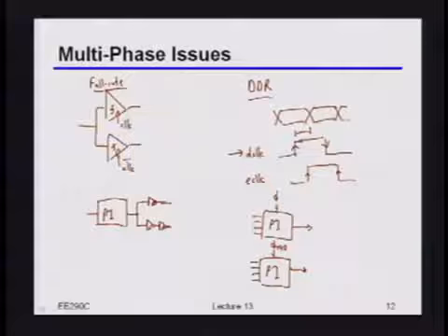So it's not to say that it can't be done, but it turns out there's a sufficient amount of annoyances with doing things this way that people actually came up with a few fairly clever solutions that basically allow you to equivalently build just 1 phase interpolator, but actually get multiple clock phases, all with that phase interpolation happening on them, all at the same time. Okay?